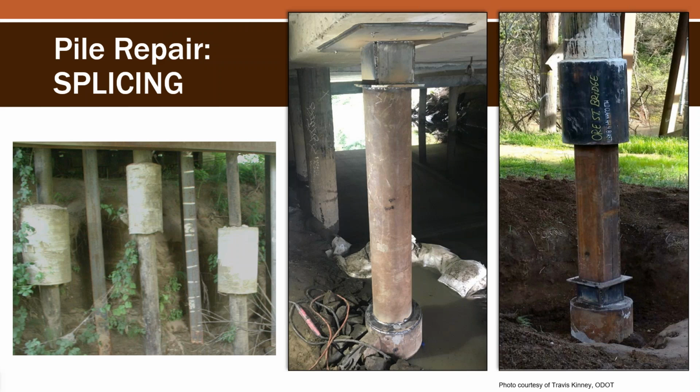That would have been an example of a bridge where the piles were probably really long, very tall bents, and there were concerns with the amount of effort and bracing that would have to be ripped out in order to actually do a full height. Typically, full height is the way to go.